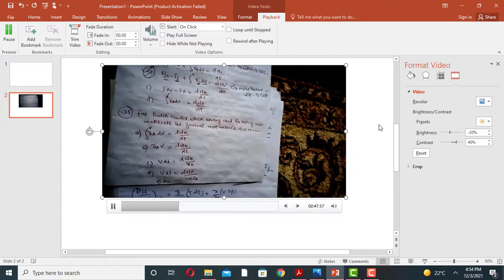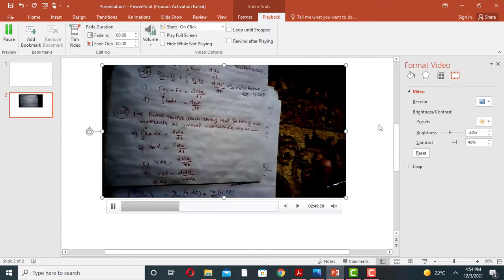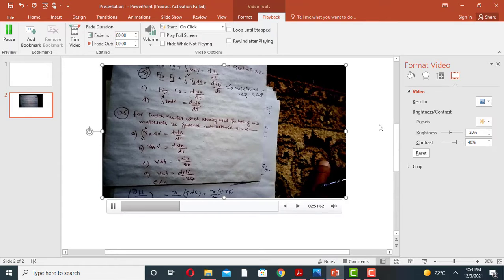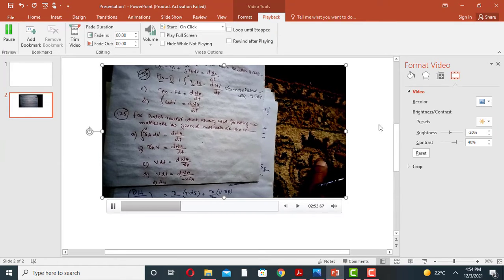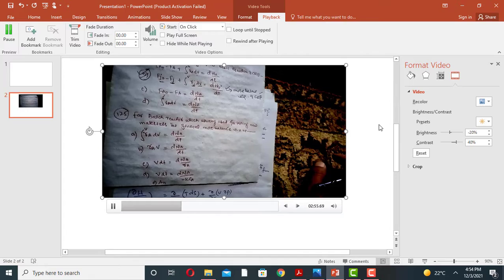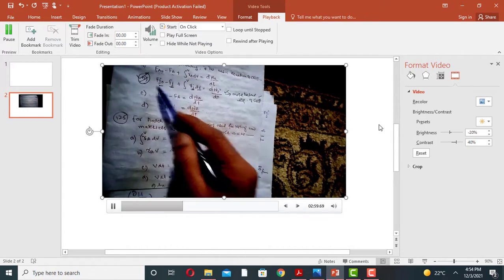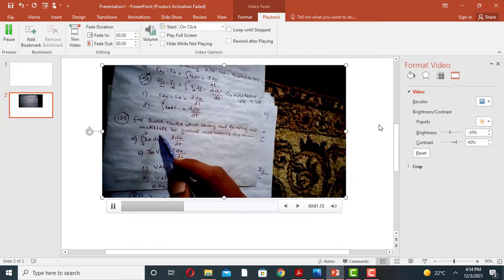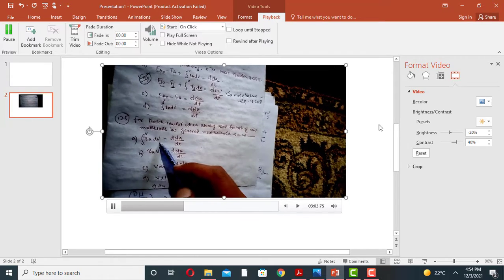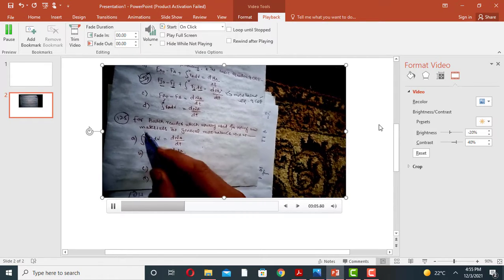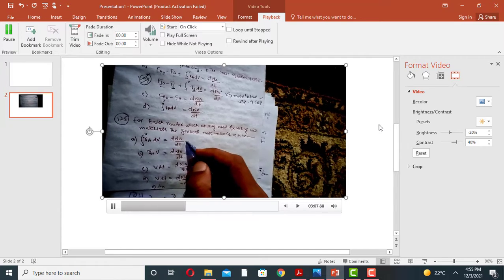For a batch reactor, which is usually used for testing new material, the general mole balance equation will be: in a batch reactor there is no input and no output, so input and output are 0. So this will be equal to this: rA times dV, and V is equal to dNA by dt.